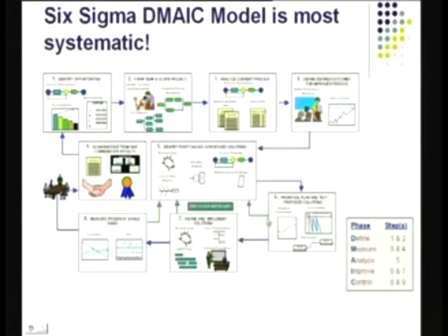The factor effects are found right here, if you might remember, and you can go back and view the lectures on design of experiments one more time. That will tell you which factors are important, which are not, and for the factors that are important in delivering quality, what their optimum settings should be. These are discovered by doing DOE, design of experiments.